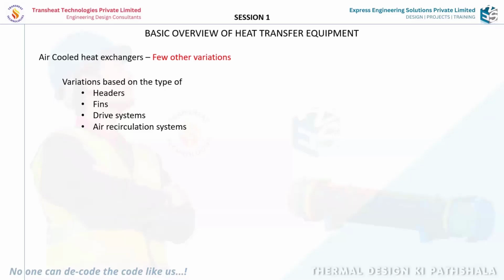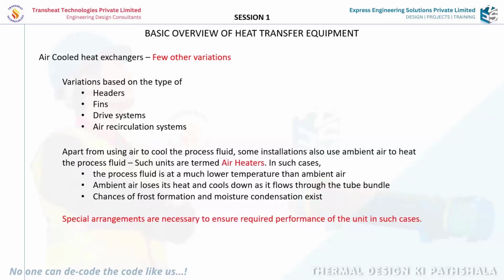So in such cases, we use ambient air to heat that fluid. Like if you have your fluid at around -20, -30 degrees centigrade, instead of using any other type of heat exchanger or utility stream, we can always use ambient air to heat that process fluid. Of course, there are some additional considerations which you have to account for. Typically such units are called air heaters because we are using ambient air to heat that fluid.